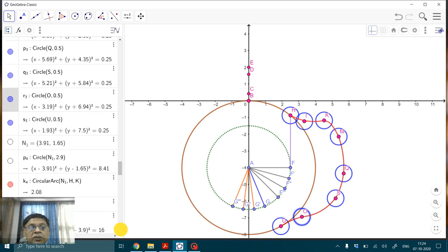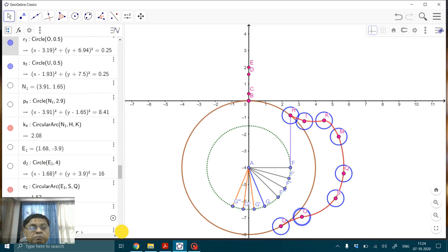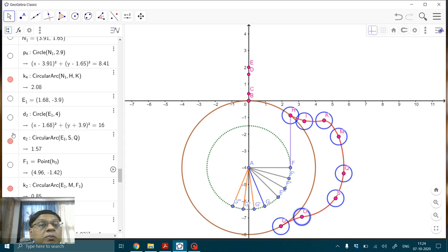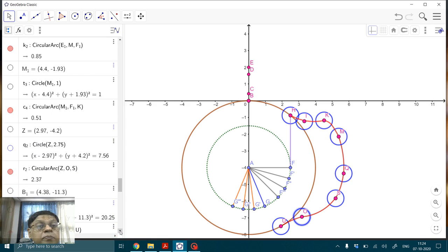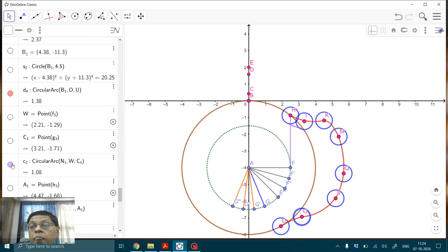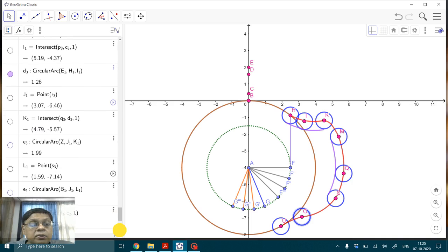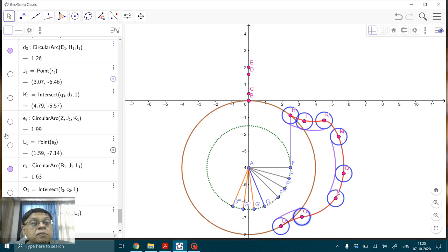And then the idea, as I have said, is to draw a curve which is tangent to these circles. Basically it comes up with this. I have already done that. Let me see what I get. So this is kind of a crude construction, where I've tried to keep it as tangent as I can. It didn't come out too well, but that's fine. And then the last part is the circular part of it. So you can see I've completed the construction of an offset roller follower.